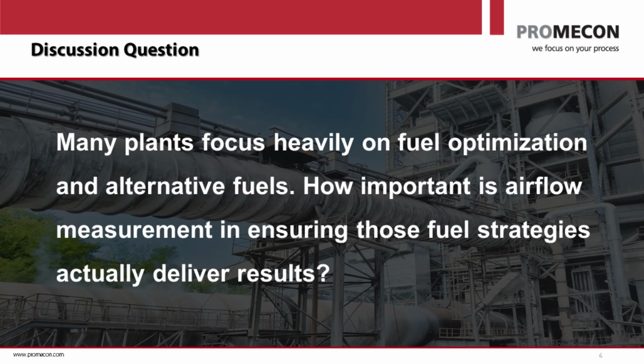So although continuous airflow measurements are not a substitute for those, they would come in addition, but since they are inexpensive, easy to implement, continuous with a refresh every second, and with almost no maintenance, they are very valuable and should be implemented until plants can also look into those kiln inlet gas analyzers and free-lime online.